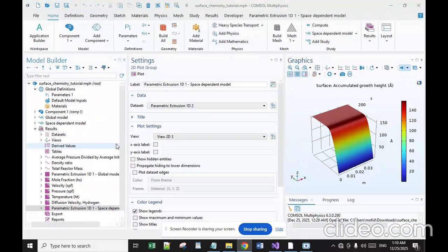The following reactions are considered on the surface of the wafer. Here (s) denotes surface species, which means that the species only exist on the surfaces where the reaction is happening. To indicate that a species is bulk, append (b) to the end of the species, since bulk species cannot participate in surface reactions. They must only be products and not reactants in a surface reaction.